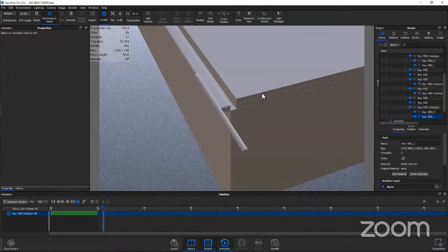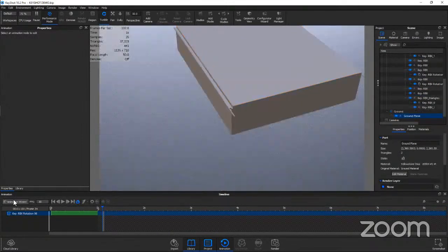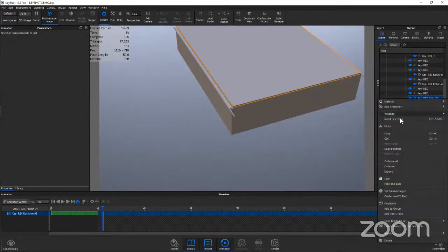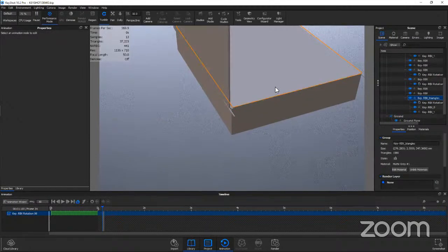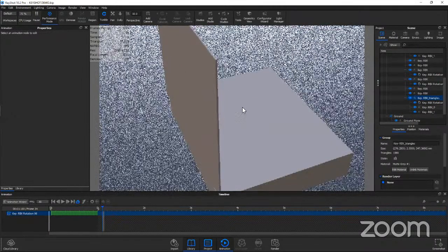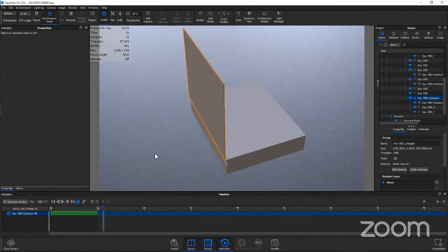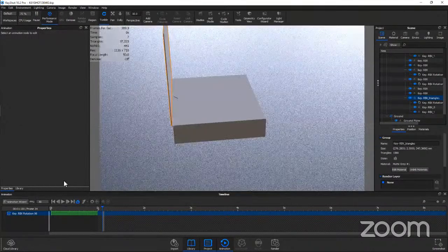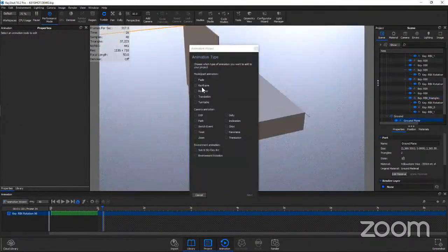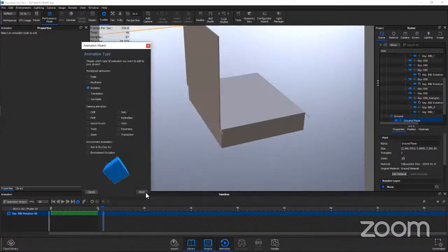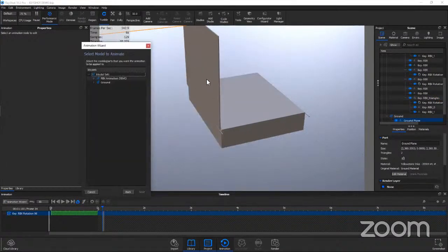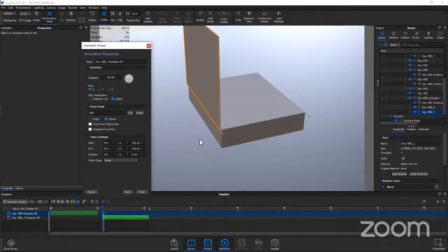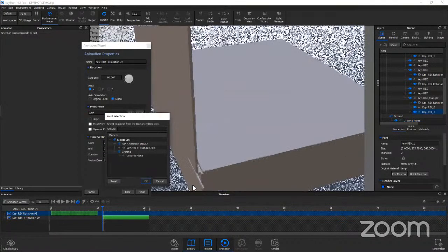Now I'm gonna move this lid next. So now you have it in this 90 degree, but now I want to fold it even more open. So I'm just going to add in another animation. I'll pick that new pivot point down here.